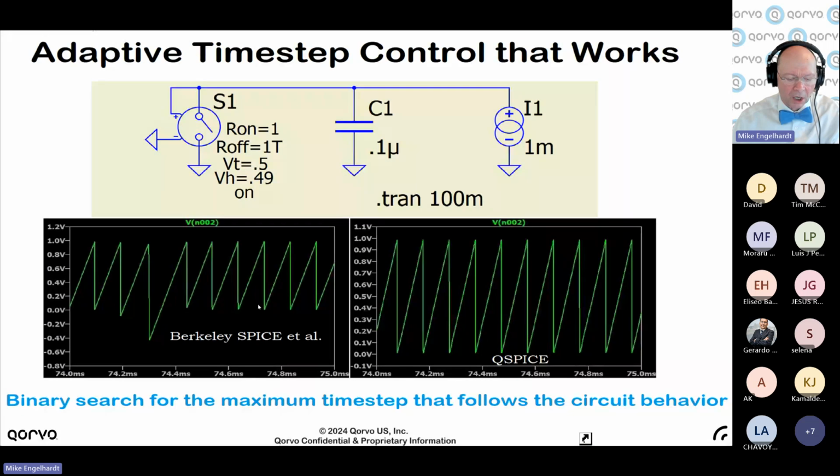One is that when I talked about eliminating device IV curve discontinuity so that you could analytically iterate to the solution, a core part of the SPICE algorithm is it relies on continuous IV curves, and a hysteretic switch doesn't have continuous IV curves. So people kind of tolerate that it's outside of the scope of what the solver is trying to do. And besides, if you stipulate a very small time step, this waveform cleans up.